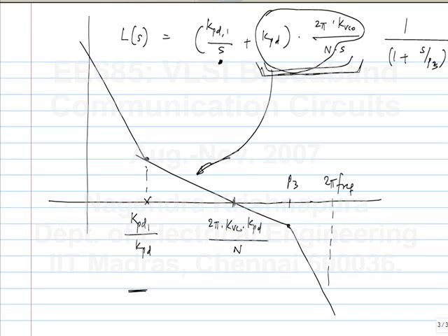Okay. So this, we kind of started by constructing a first order system and then added a second integrator to improve the DC performance and a third pole to improve the attenuation. So the conditions become very clear here, that is condition for stability and so on. These points should be in this order basically, right? KPDI by KPD, this should be significantly less than this, so that it shows a first order behavior here.